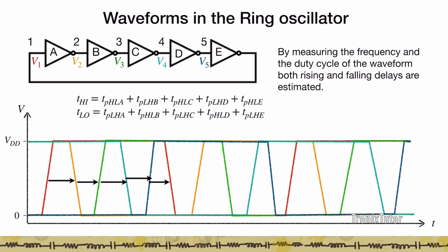So this is a very common structure we normally place on test chips, and this is done to evaluate our silicon to spice. When we want to evaluate our spice models, when we want to test silicon, when we want to build models for silicon, one of the first test chips in the technology typically has ring oscillators.